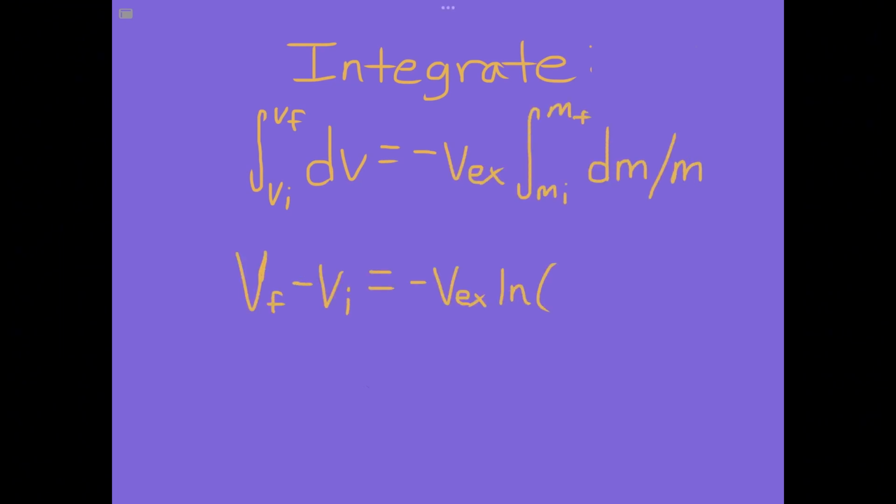The final step in achieving the ideal rocket equation will be integrating to find a change in velocity. The final ideal rocket equation can be seen here. This is in relation to free space. In other words, air resistance, drag, and gravity do not come into play.